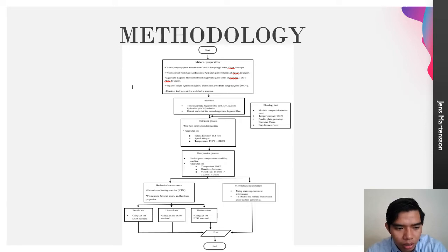For the pre-treatment, the sugarcane bagasse fiber will be treated with 3% sodium hydroxide solution. Then it will be rinsed and dried. Before the extrusion process, rheology tests will be conducted to know the viscosity and the flow behavior of the material. For the extrusion process, the twin screw extruder will be used, and the parameters set are screw diameter 15.6 mm at speed 60 rpm and temperature 190 degrees Celsius to 200 degrees Celsius.